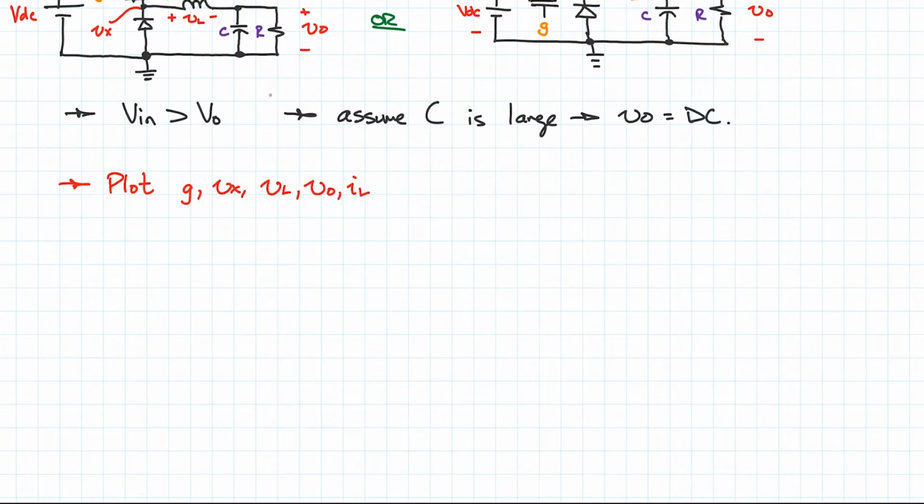Analyzing these circuits based on waveforms, plots and subcircuits is probably the simplest way, because you have a number of different circuits based on different switching conditions. The easiest way to relate everything together is to figure out how the circuit behaves over one period.